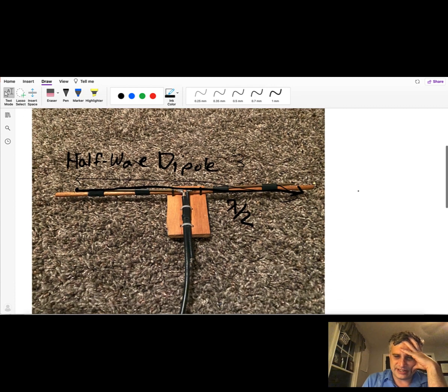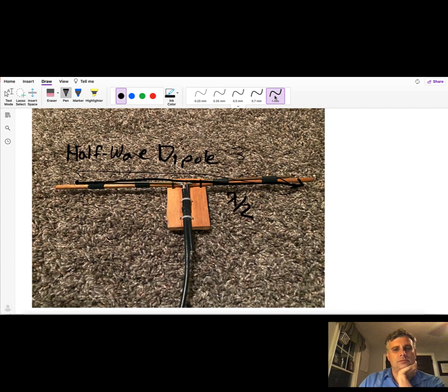So back to this antenna here. We see that nice piece of metal here. Here it's being fed by a coaxial cable. The inner conductor of the coax is soldered to one arm. We often call these arms of a dipole. And the ground plane is soldered to another. Now there's this really interesting structure here. It looks basically like a section of coaxial cable that has been glued to the side. It's actually electrically connected to the ground sheath on both ends.